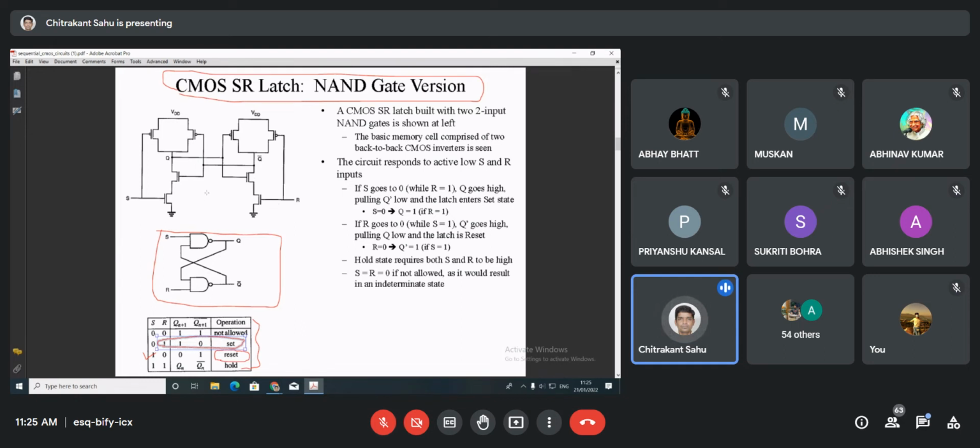So you can just prepare a NAND gate similar to the previous one, again one NAND gate, and then make the interconnections. So how many transistors will be required to make an SR latch? 8. 8 transistors, correct. I'm not going into the details, so that you can build any kind of CMOS circuit if you know the logic gates. And you also have to remember which technique you are going to use for the universal gate.